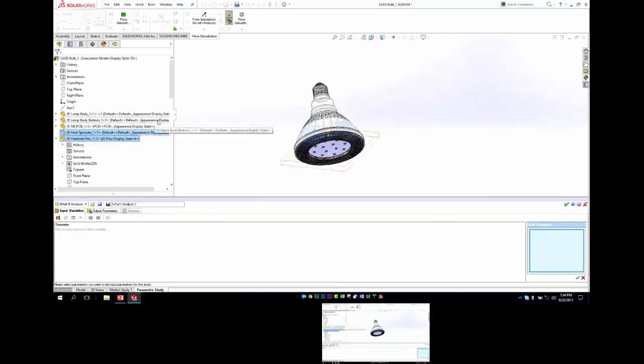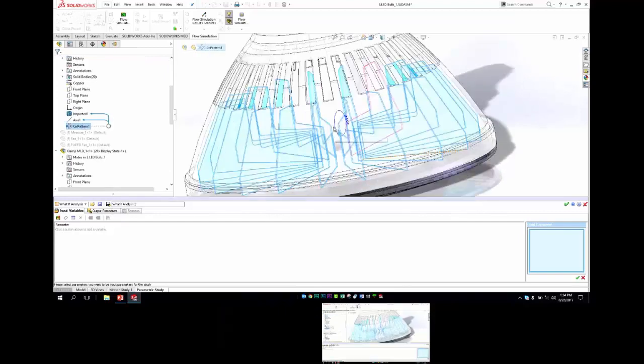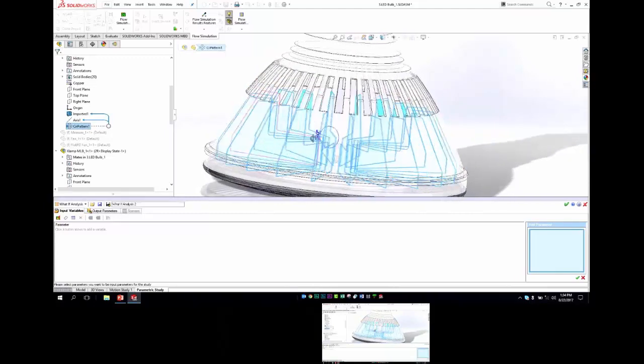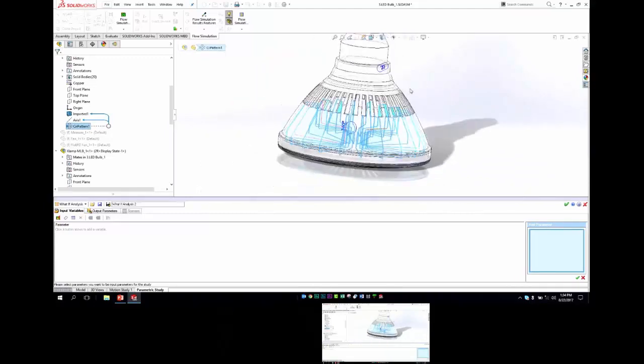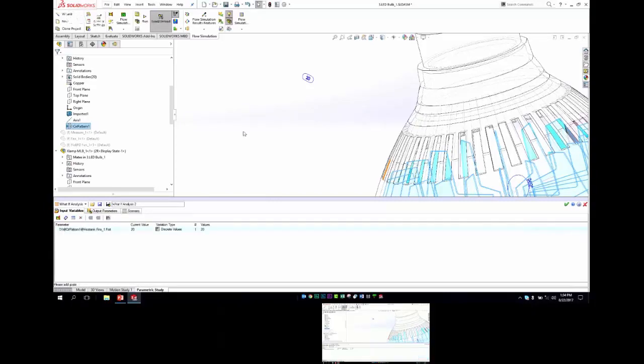And so my heatsink, I have a circular pattern on my heatsink. You guys know SolidWorks, there's nothing new here. Obviously my heatsink goes around 360 degrees, and I have 20 instances. Well, simply by clicking that 20, you'll notice that parameter is now in my parameter list. So I can control that parameter now. Pretty cool. So how do I want to control that parameter?